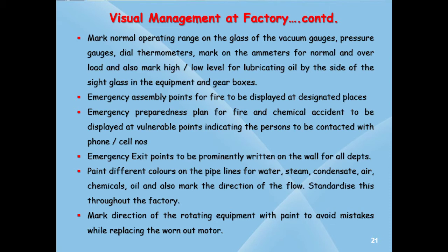Display of signboards at the emergency assembly points and also indicating the important emergency phone numbers to be contacted in case of fire or chemical accident, etc. Fix which color to be painted on the water, steam, condensate, compressed air and oil lines. Also mark the direction of the flow in the above pipelines.